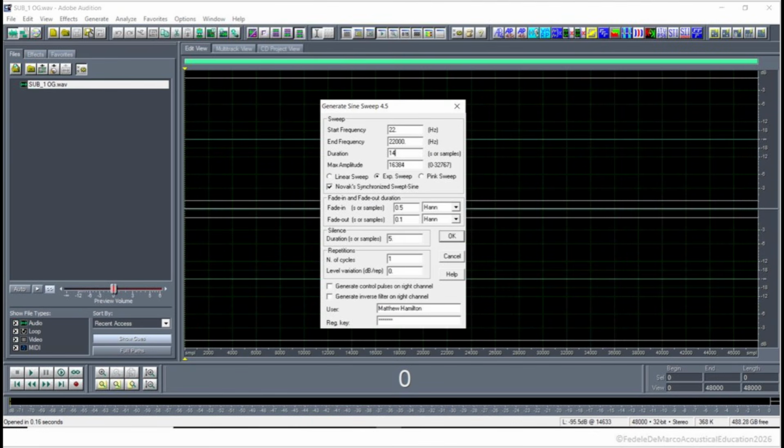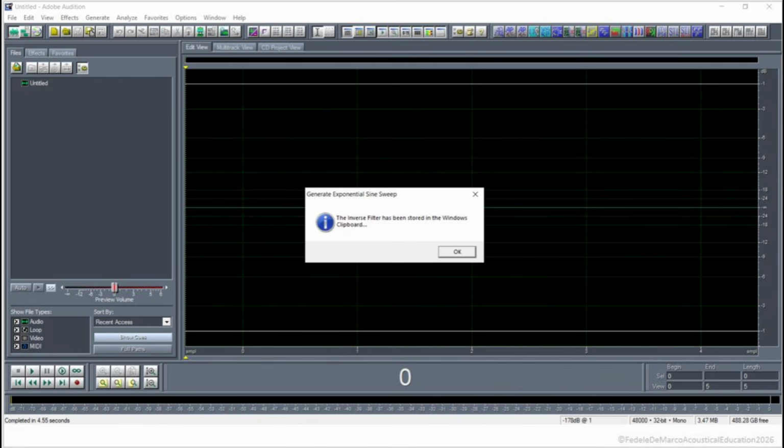Now, let's open the first of Professor Farina's plugins from the Aurora Plugins suite. Navigate to Generate in the toolbar and open the Aurora Sine Sweep Generator. Typically, these plugins are ready for most common applications by default. In this module, you can select the type and characteristics of the test signal. For this case, we will generate a 14-second ESS. You can adjust the parameters shown according to your specific needs. We generate a mono signal, which appears in the left panel of the editor view.